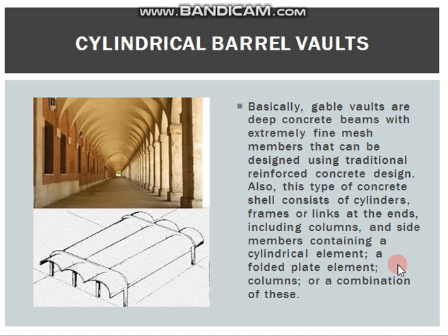Example: cylindrical barrel vaults. Basically, barrel vaults are deep concrete beams with extremely thin members that can be designed using traditional reinforced concrete design. Also, this type of concrete shell consists of the cylinders, frames, or links at the ends, including columns and side members containing a cylindrical element, a folded plate element, columns, or a combination of these.